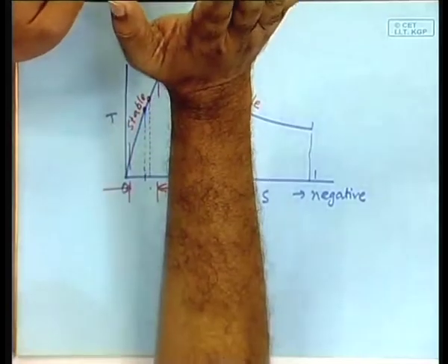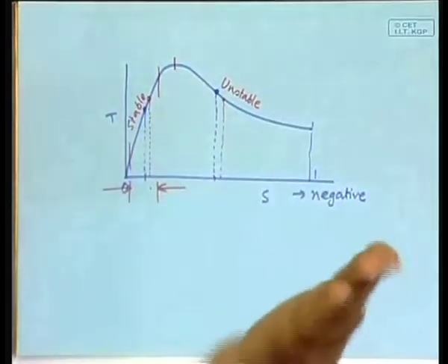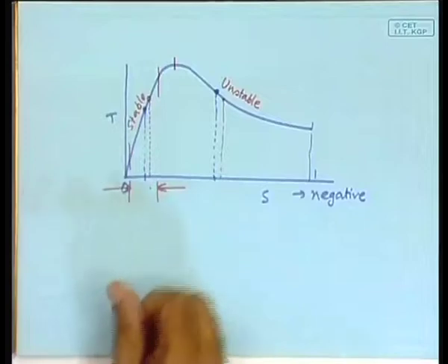At present time, I am talking about 2007, India has about 3000 megawatts of wind electrical generation capacity. It is a large amount, and almost all of them are simple squirrel cage induction generators connected to the grid, which means they effectively have no variation of the speed really, and that is actually maintained by variation of the pitch angle. Why? Because this is cheap. The squirrel cage induction generator is very inexpensive. So, if you are buying on the basis of the lowest quotation, obviously this wins, because this is cheap and very rugged, nothing really happens.